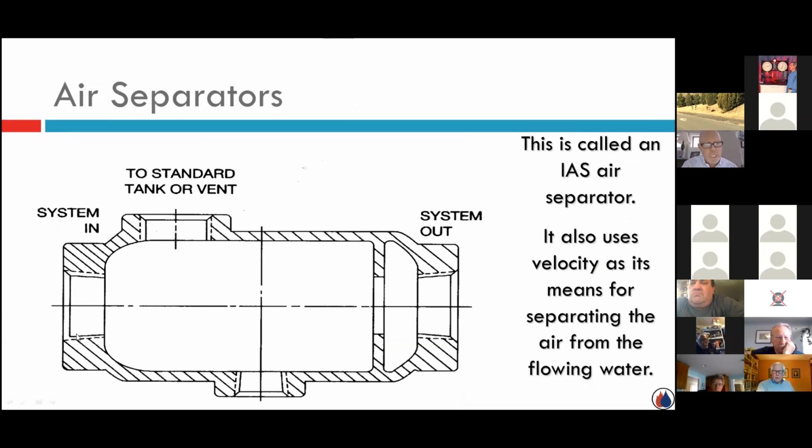I have a 1.25 inch air scoop. So this is the diameter right here. The engineers would make sure that the air scoop's diameter internally would be such that when the water was moving at 4 to 5 feet per second, that's the standard, and you would have learned that through that system sizer class we took last week, as soon as that water enters this air separator going 4 to 5 feet per second, it immediately would be reduced to a half foot, 6 inches per second, a wide spot in the river.